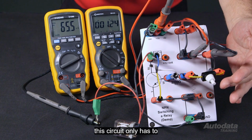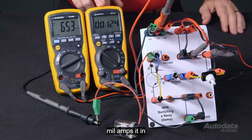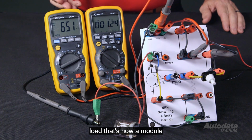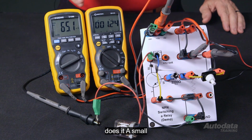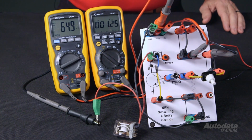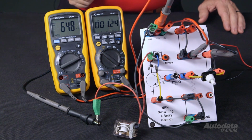So the switch in this circuit only has to be able to flow 1.25 milliamps. It in turn turns on the relay, and the relay can now switch a much larger load. That's how a module does it. A small signal operating a larger control that can operate a relay, a component, or whatever.